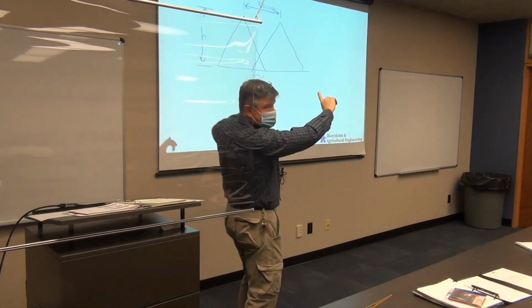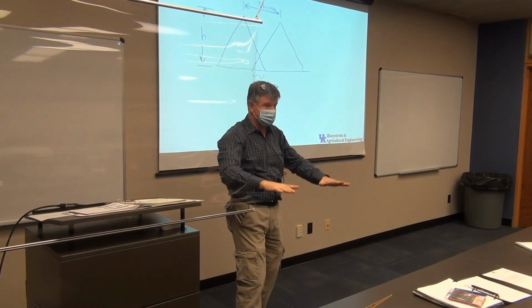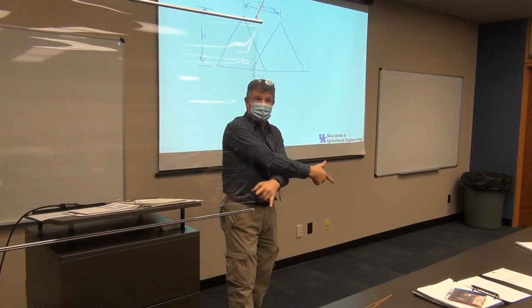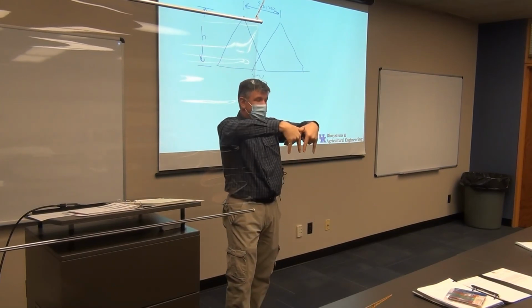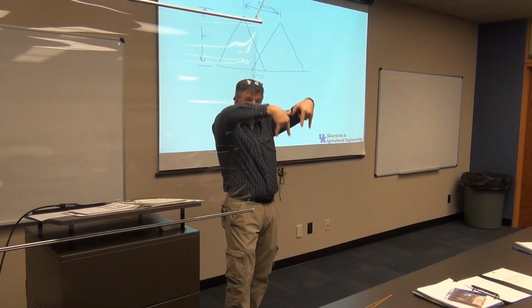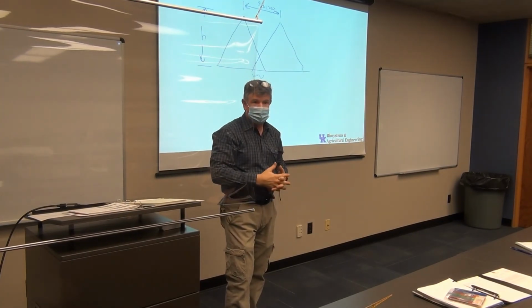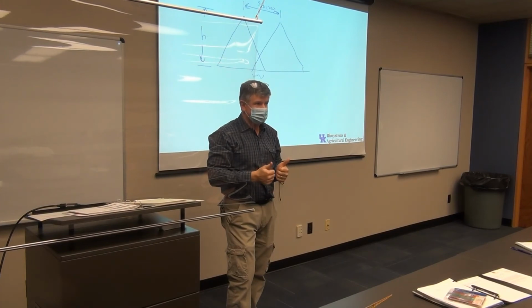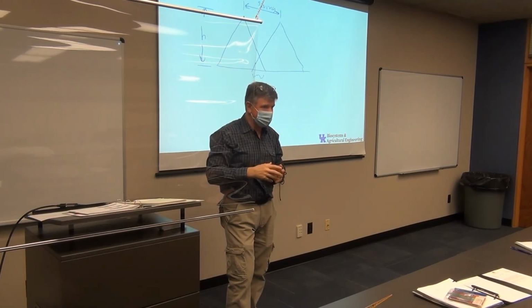So that's going to change. If I got a really wide pattern, now I'm going to need to push that boom down because those things are really going to overlap. So I need to run that boom lower to the ground. If I have a narrower nozzle that shoots more straight down and not so wide, then I can raise my boom up. So that boom height is going to be dependent on that. Okay? Is that settling in a little bit now?